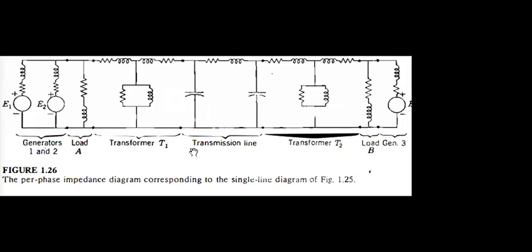And this is the transformer T1 part, where you have the equivalent circuit, something like this. That means you have the core loss path and copper loss path. These are the shunt paths, and you have some resistance and inductive configuration. That is the impedance for what we can say is the input impedance or the primary impedance for the system. And this part you can consider as secondary impedance, which is converted to primary side. Okay.